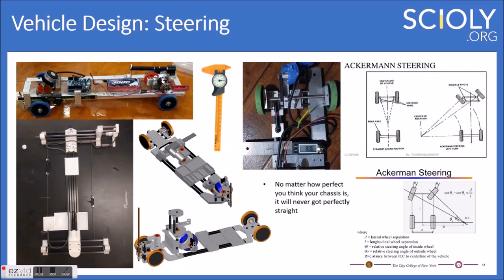You can see this Ackerman steering. You can do this fixed curve or have a servo there for that. And so it's a little bit more complicated. It might not be completely necessary, but it's going to minimize any slip problems that we'll talk about later.